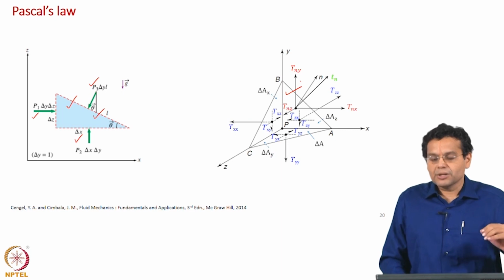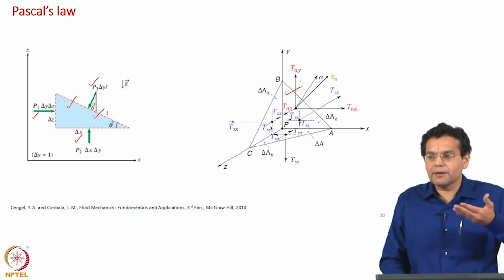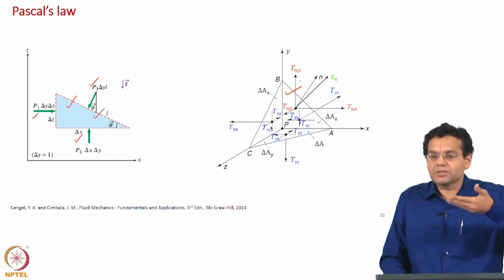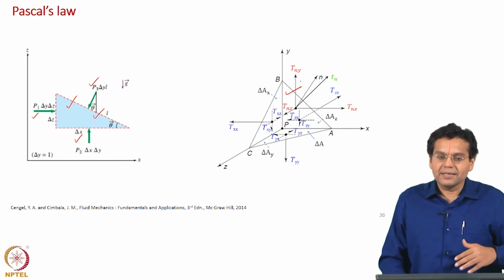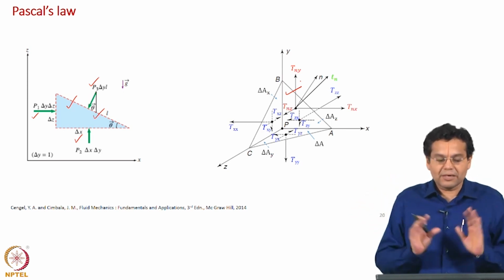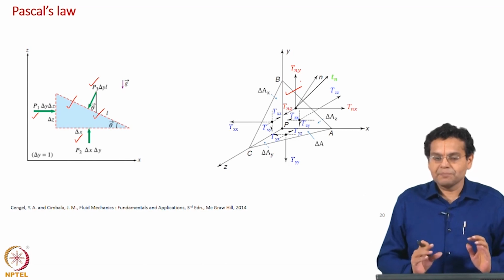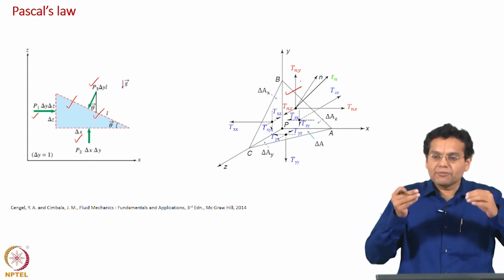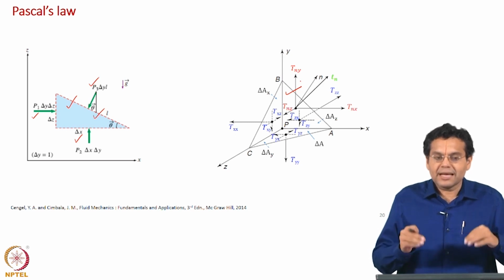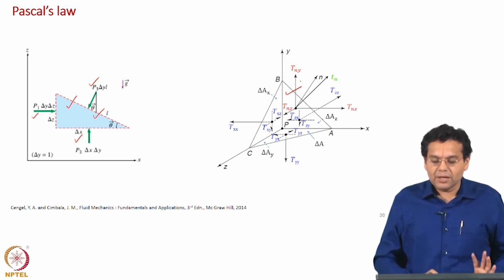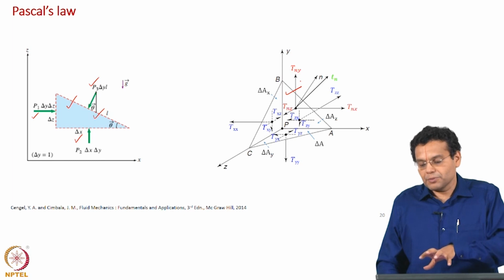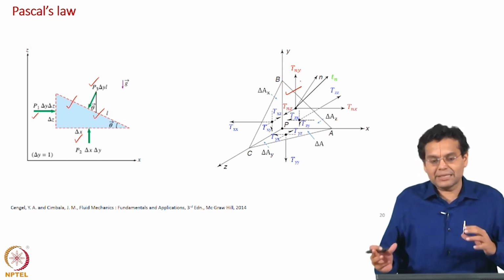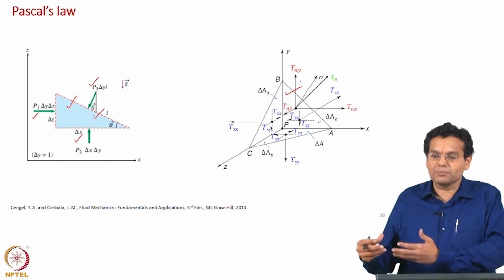Pascal's law is derived in, let us say, second chapter of fluid mechanics book, and a fluid mechanics book slowly gradually develops fluid under rest condition, then without viscous forces, with viscous forces etc. So, because it is considering fluid under static condition, they do not talk about a general stress, they talk about only pressure as the only normal stress. Because we talked about a general stress, we said more physically fluid under static condition has only pressure as a normal stress. Okay. So, they are more specific and discuss only pressure, we are more general saying Txx, Tyy, Tzz, but finally of course we also came down to pressure only.